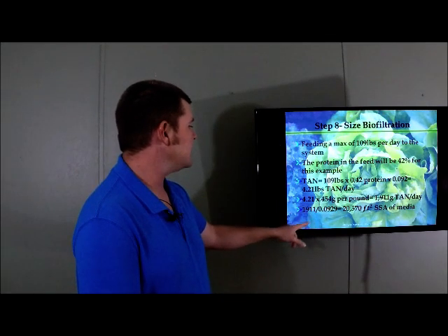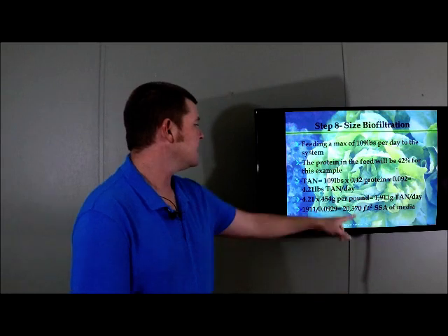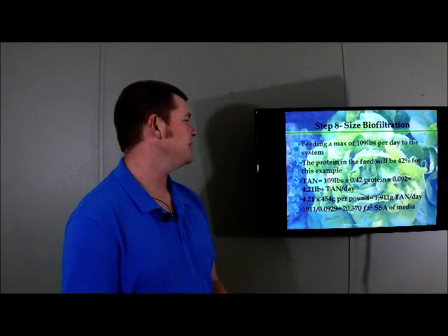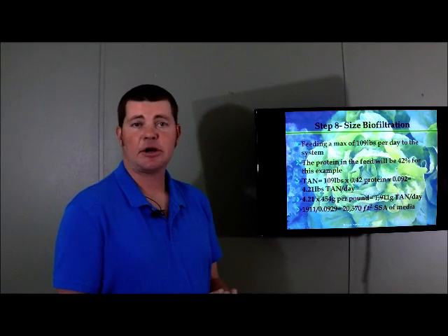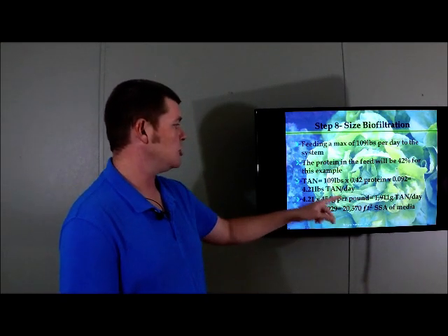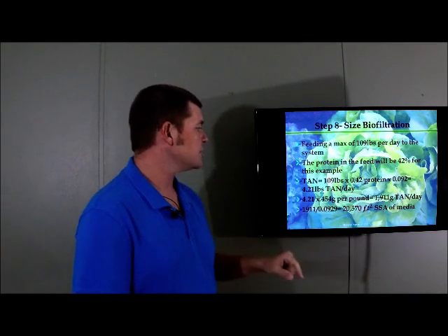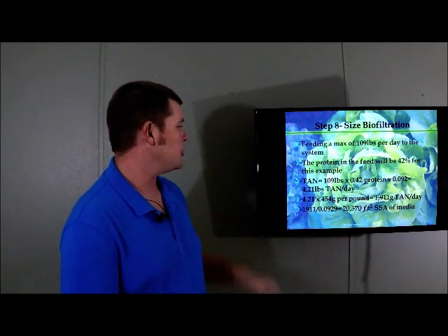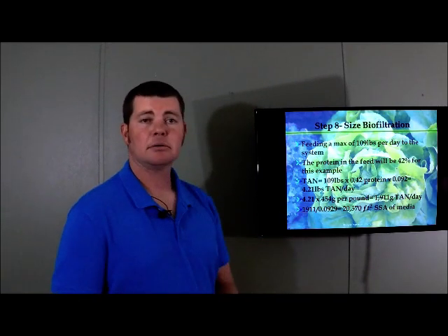1,911 divided by 0.0929 gives us 20,570 square feet of SSA, of surface area on the media that we need to process it. And of course, if we're just using square meters instead of square feet, it's 1,911 square meters because it's 1 gram per square meter. Okay?